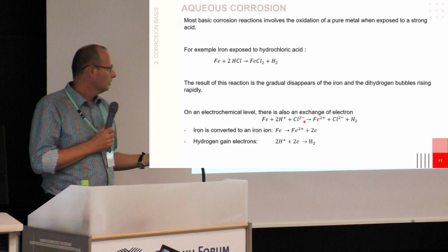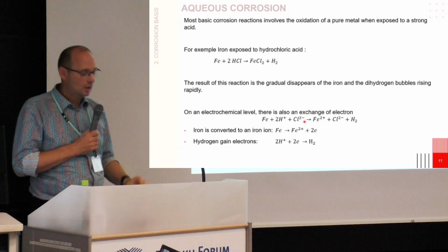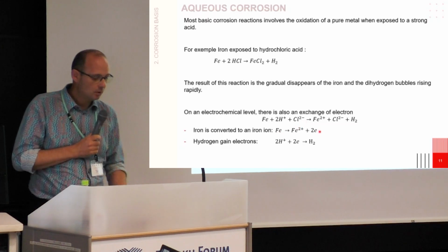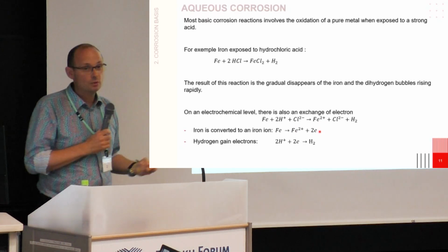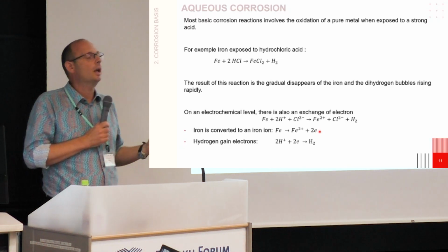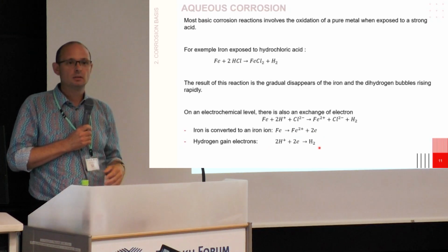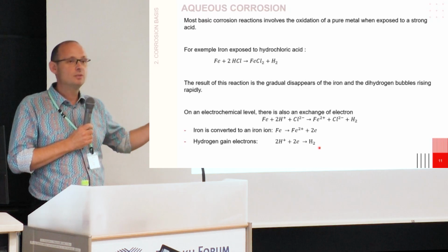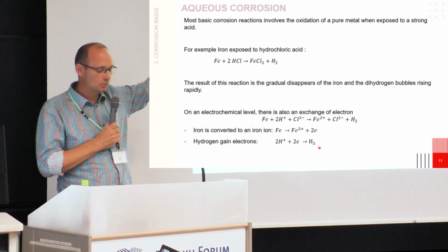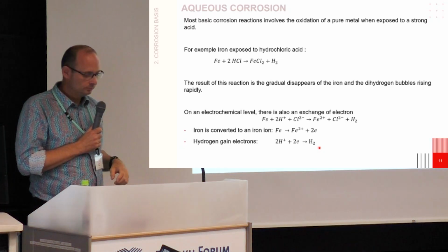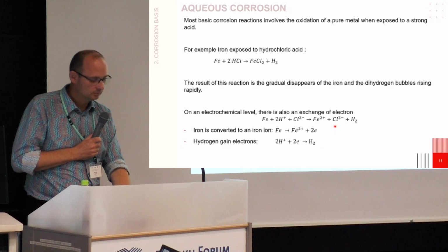And if you have that, and you look at what kind of reaction can happen, it's an electrochemical reaction. If I'm watching, iron can dissolve, releasing 2 electrons. These 2 electrons can be caught by who? H+. And if you take 2H+, you will get H2, dihydrogen. If you perform this experiment, you will see that there is a lot of bubbling appearing around the steel rod. So finally, the equation is more something like that.